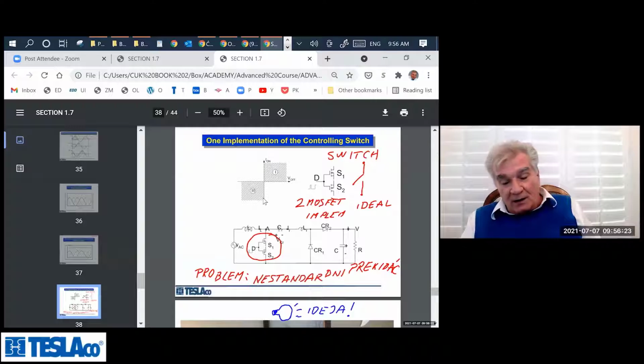So I have to fake it with a composite switch, which has two MOSFET switches back-to-back with a drive between them, and the sources are connected together at this point. You have to have a floating drive to drive these two switches, because you're driving between the drive and this common point. Or you can have two IGBTs which have reverse capability and then put them in parallel.